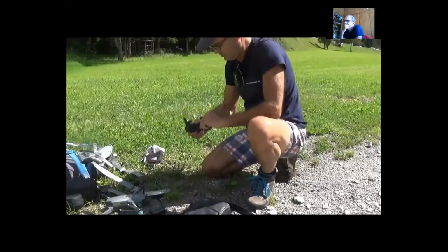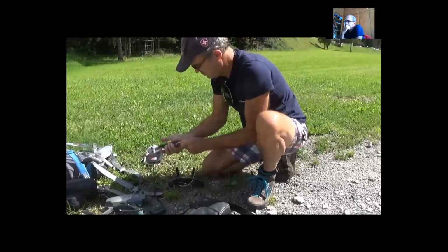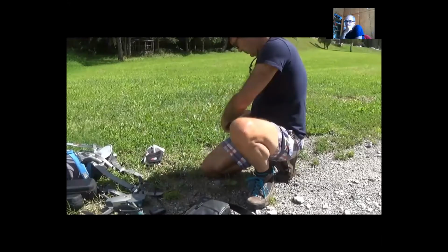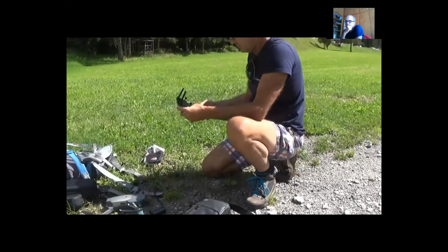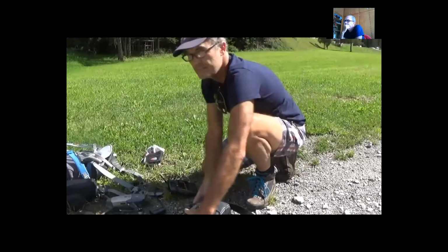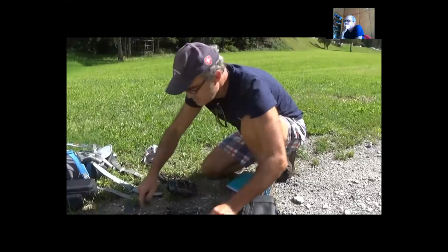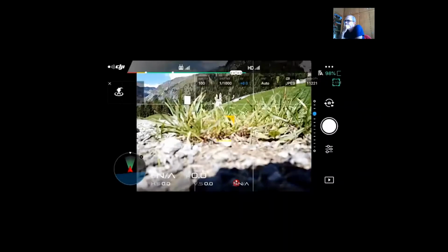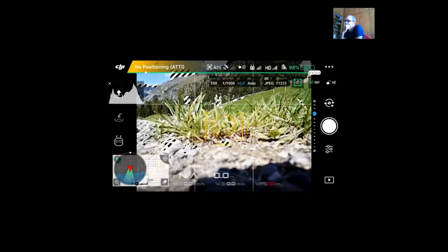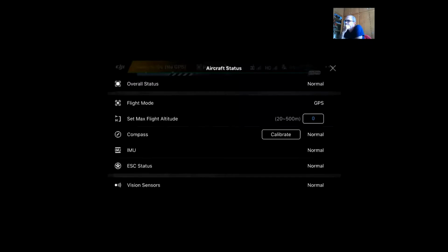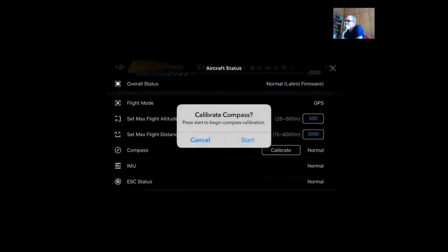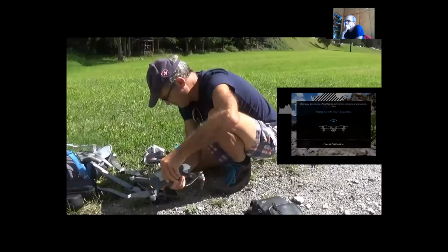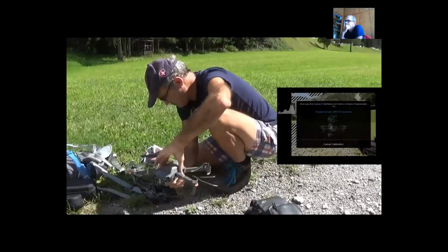Find a clean takeoff space, connect your drone to your mobile phone and open the application DJI GO 4. At this point, your remote control should connect to the drone, your mobile phone should connect to the remote control, and you need to calibrate your drone in order to have a better flying precision. Once this is done, you can close the DJI GO 4 application.